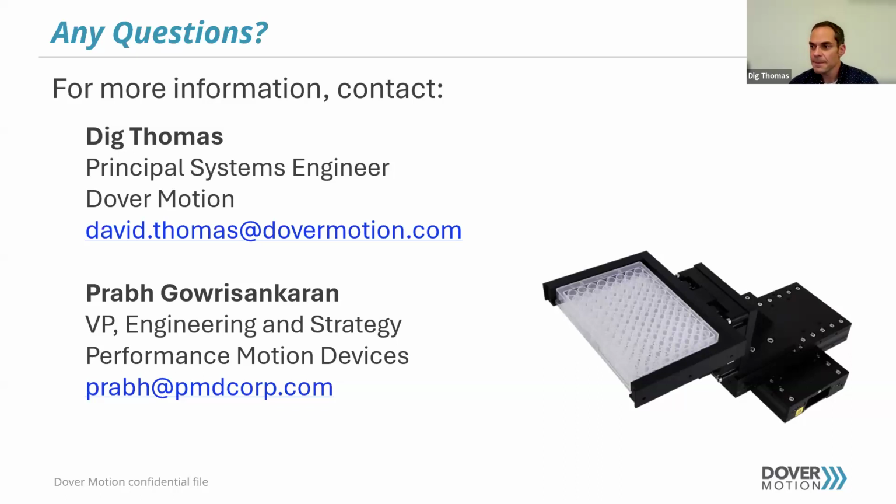Great. And we're at time here, so I'm going to end with one more question that came in. Can I set up outputs to indicate when an axis is in motion or settled? So yes, you can. There are a few ways of doing that. The most common way is through a breakpoint. You basically choose the output you want and set the breakpoint to trigger once you have settled, and you will see a 5-volt signal go high, and that's how you do it.